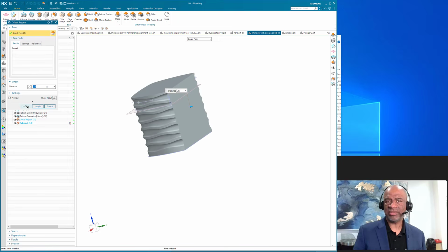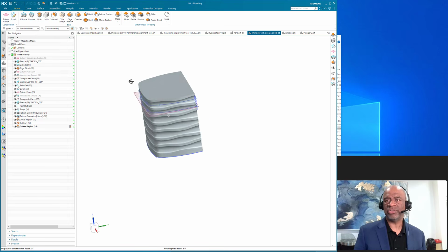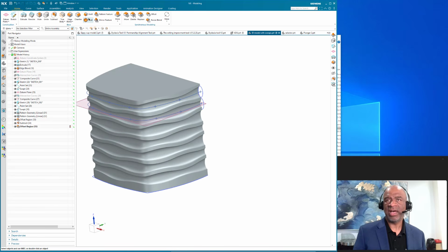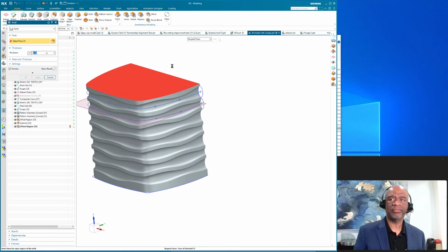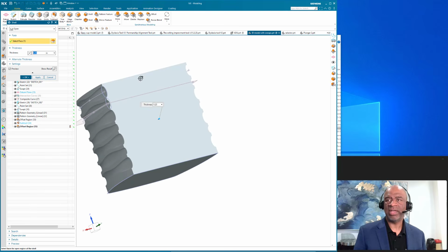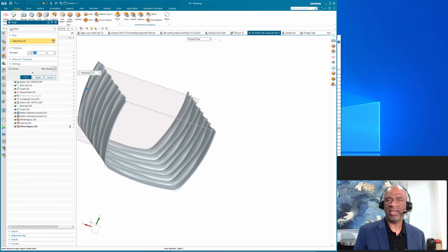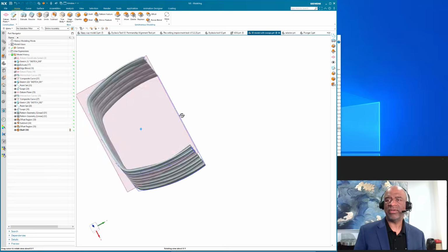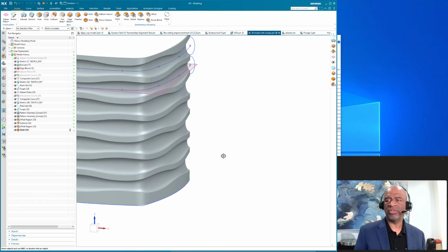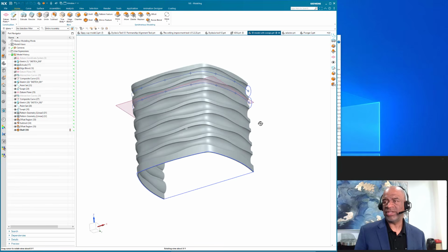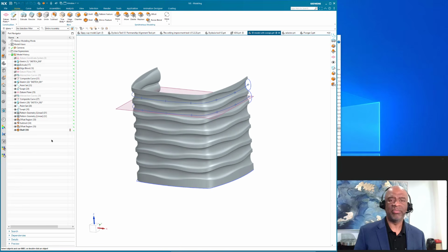I did that because I was thinking that the cutters would be face on face, and that's not a good thing. I'm going to shell the whole thing out, shell this face, and this back face, and this bottom face, and say OK. And oh, before I shelled, I think I wanted to smooth out these edges with a blend.